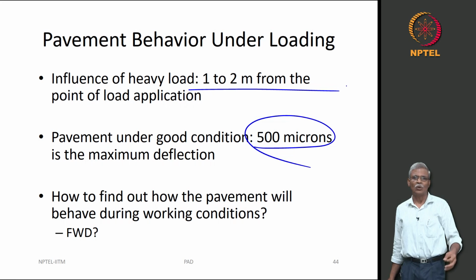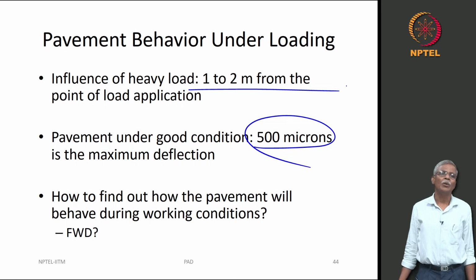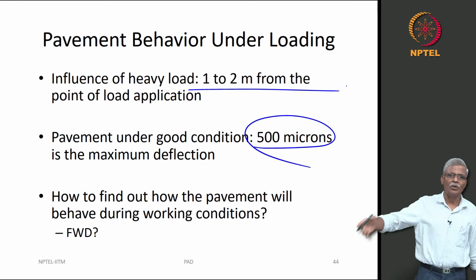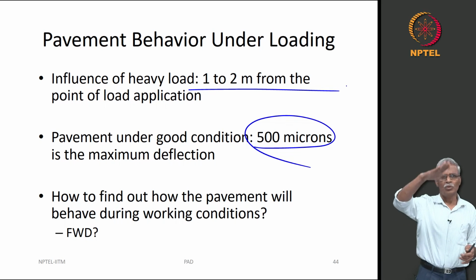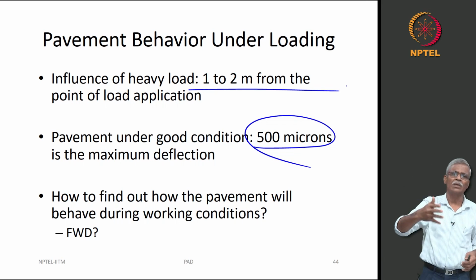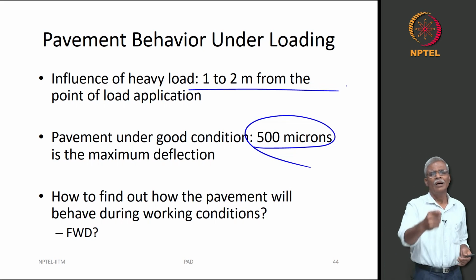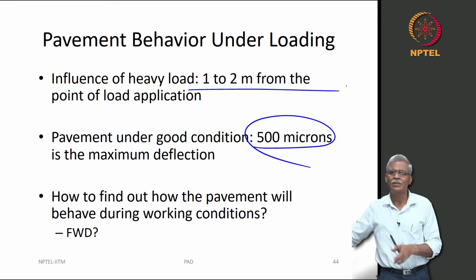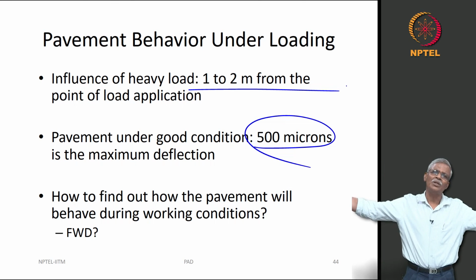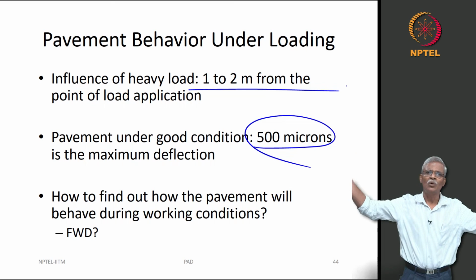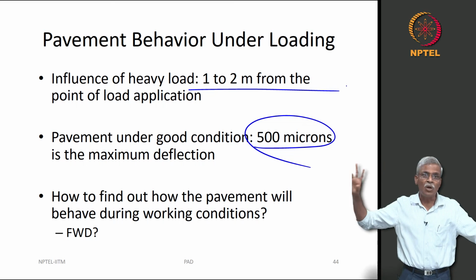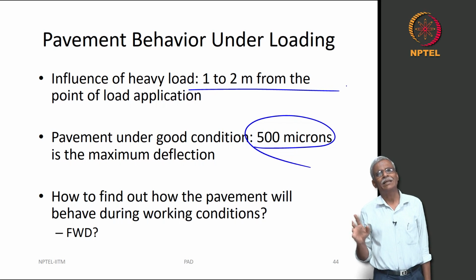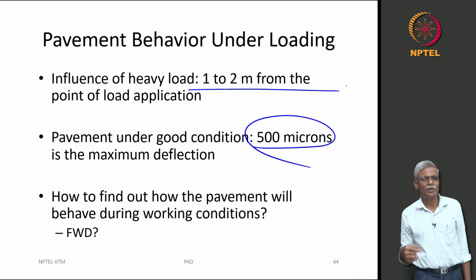So, when I take the load, this is an analysis that you should be able to do in KenPave. You take a pavement and you have many cross sections there, apply the maximum load. You do not need to worry only about 560 kilopascal. What happens if there is an overloading? Apply 1000 kilopascal, apply 2000 kilopascal. Use your KenPave analysis and go on all the sites, try to see when the deformations will become 0, and if it is going to extend beyond 2 meters, okay, then you are basically not looking at a great design. So, this is your design that you need to really worry about.